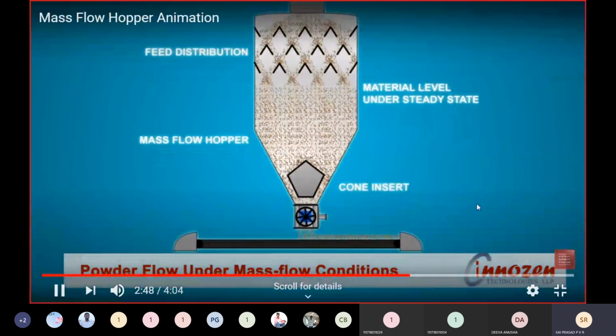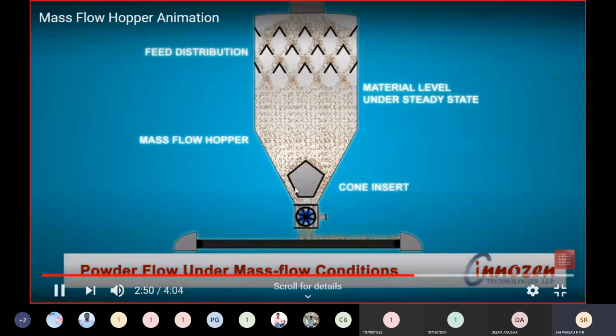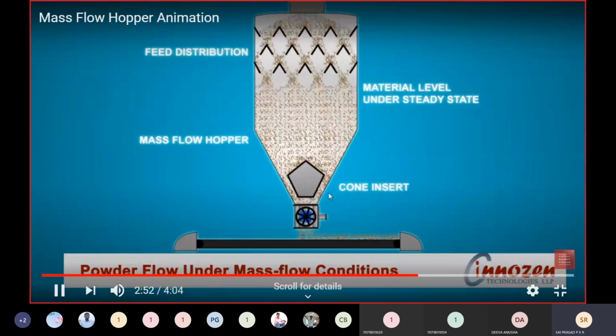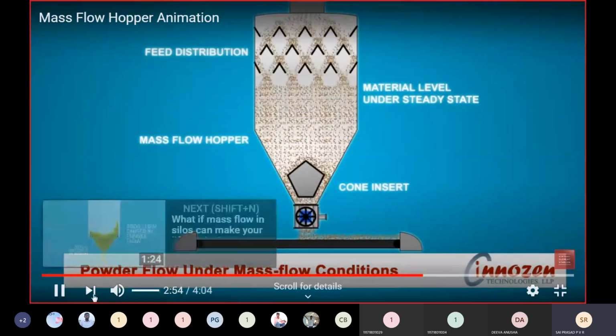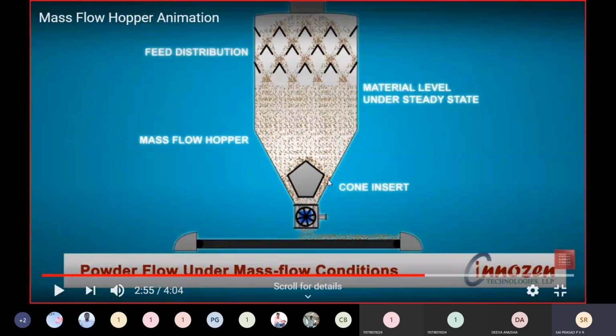To avoid any type of increase in the pressure or jamming, etc. Because when the material does not flow, there will be pressure. When the material does not flow here because of the arching, what will happen at this particular location? The pressure increases. Thereby there will be uneven distribution of pressures, and there will be a failure. Hence, to avoid the accumulation of solid particles here, or to give dosage continuously to the other one, we keep a cone here like this so that it divides the flow, and from the sides it comes out.